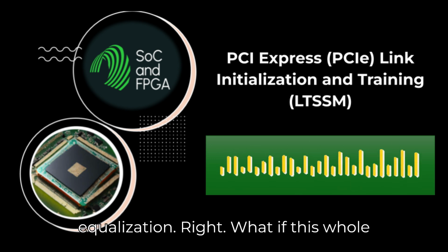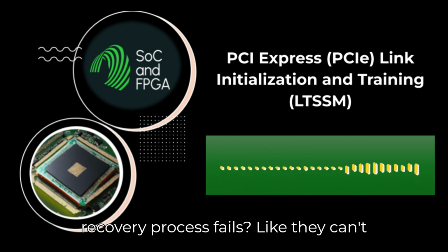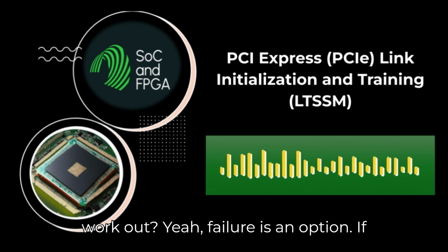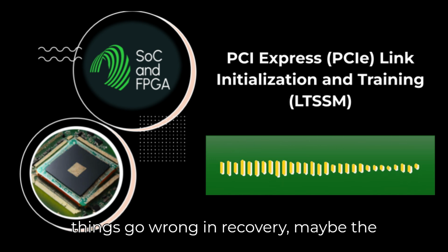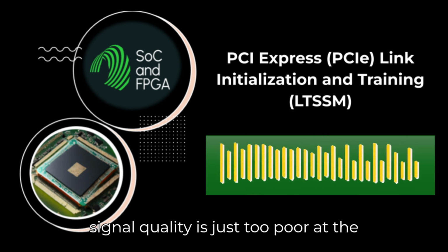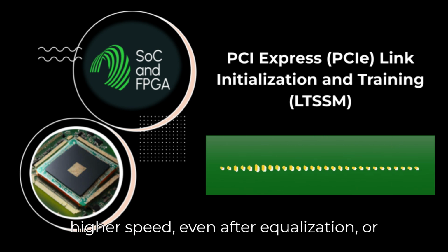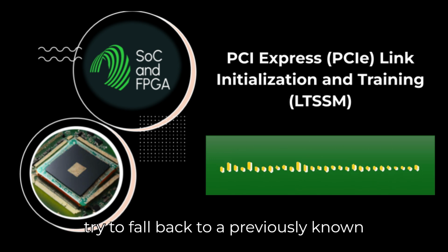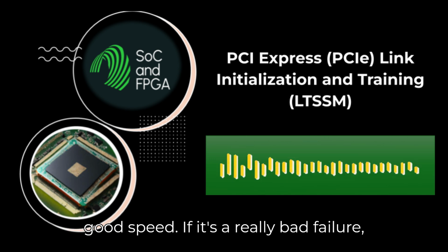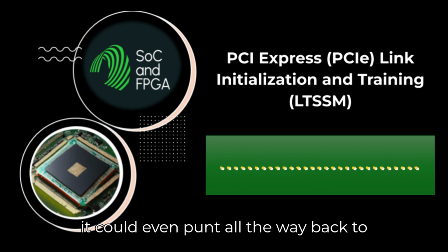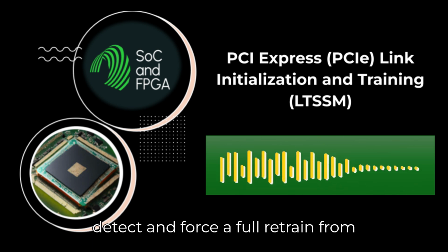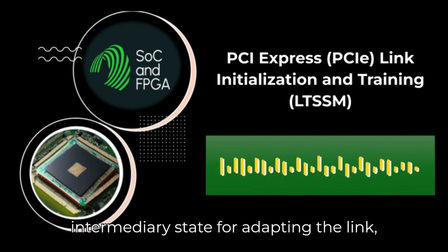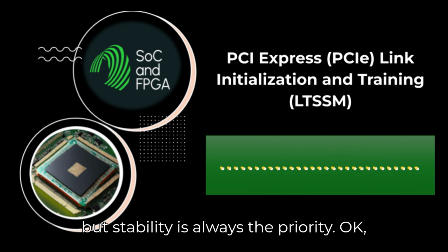Equalization. Right. What if this whole recovery process fails? Like they can't agree on a speed or equalization doesn't work out. Yeah, failure is an option. If things go wrong in recovery, maybe the signal quality is just too poor at the higher speed even after equalization, or they can't lock properly. The LTSSM might try to fall back to a previously known good speed. If it's a really bad failure, it could even punt all the way back to Detect and force a full retrain from scratch. So recovery is this essential intermediary state for adapting the link, but stability is always the priority.